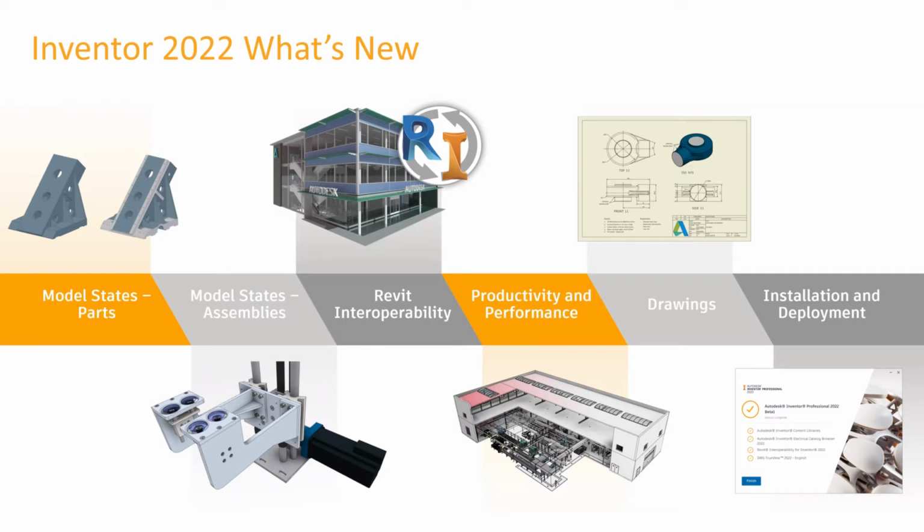So within an assembly, we can create multiple representations of an assembly within a single document, and obviously manage variations to assembly configurations and other model simplification tools that, like I said, used to be called our level of details. So level of details has now been moved off into this model states functionality. So in the 2022 release, you won't find level of detail options. You'll find a replacement for that called model states.